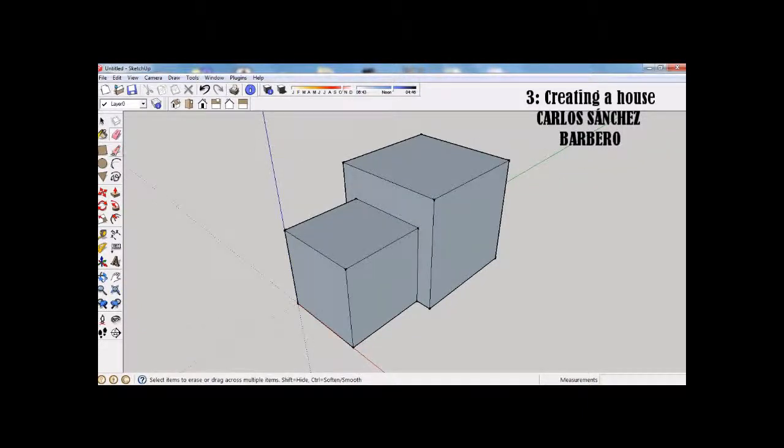Using the line tool, draw the lines that divide the oval surface into two equal parts. The midpoint inference indicates the middle point on a line or edge. Using the Move tool, click on the lines created in the previous steps.